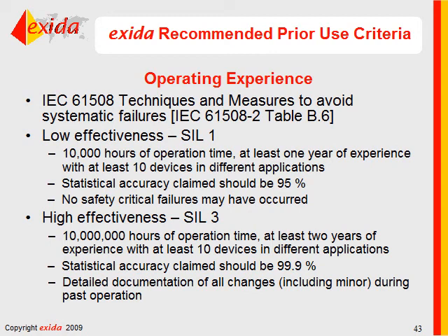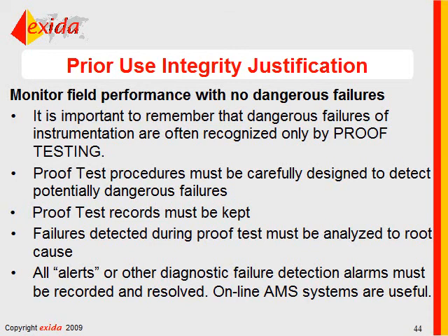There's absolutely no number of hours required or stated in 61511. Therefore, I turned back to 61508 for some guidance. When I'm involved in a certification assessment, these are the kinds of numbers that I demand before I will accept prior use evidence from a manufacturer.